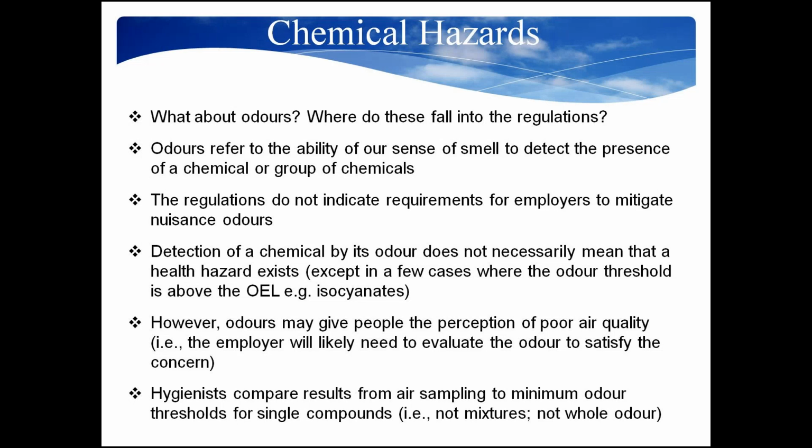Detection of a chemical by its odor does not necessarily mean that a health hazard exists. However, there are a few cases where the odor threshold is above the OEL, like isocyanates, for example. And there's a few examples out there, and that can be problematic because by the time you're smelling the chemical, you could be overexposed at that point already.